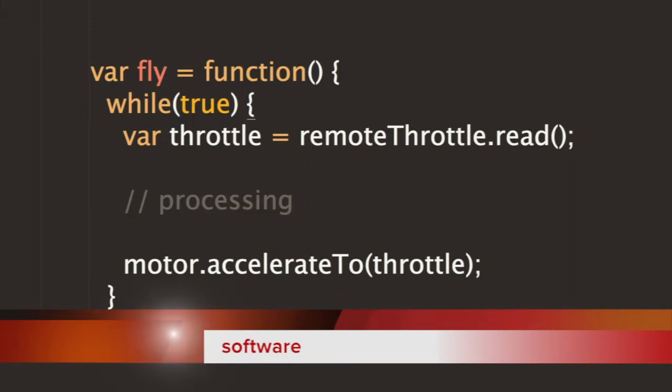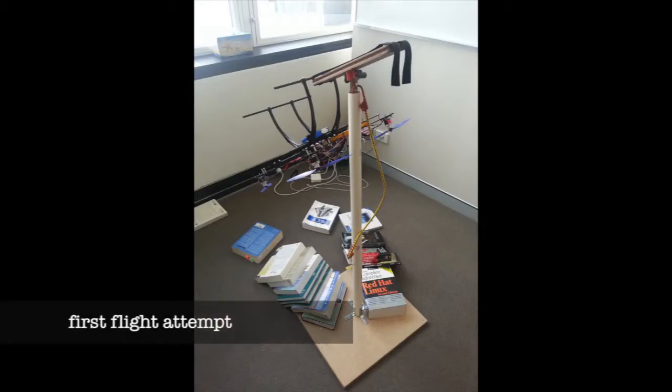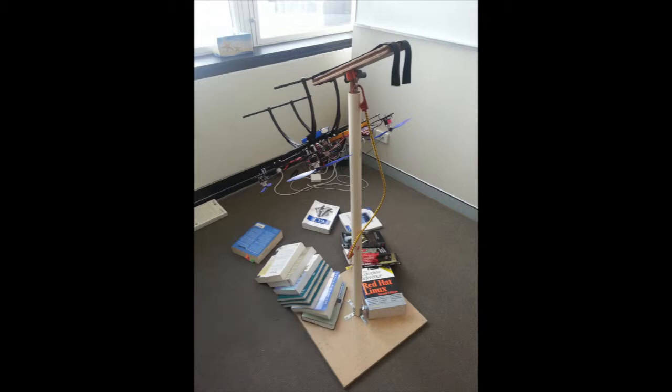The software of a quadcopter is basically a loop that runs forever. Every iteration of the loop first reads sensors, does some kind of calculation, and then writes new throttles to each of the motors. In order for the quadcopter to be able to adjust to wind and other flight situations without falling out of the sky, we need to go through this loop about 400 times per second.